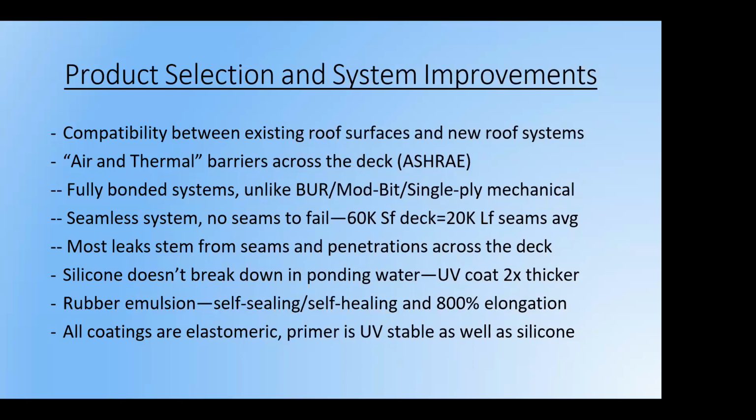Those standard systems are usually an organic based membrane, and those membranes break down in ponding water. So if it's a concern on your deck, you have a flat roof and you have ponding issues that you're not looking at, silicone doesn't break down in water. That's why over the last 10, 15 years, you've seen more silicone roof decks being put on. It's UV stable, doesn't break down in water compared to the other products, which I have some pictures we'll get into next. Next slide, please.